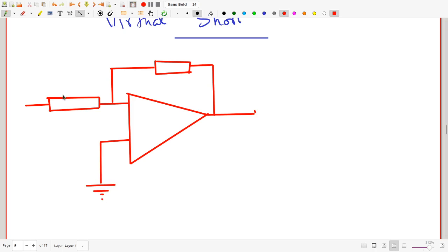So this is our inverting amplifier with two resistances, and let me just use two specific values here, 1 kilo ohm and 10 kilo ohms for the two resistors. This of course is called the feedback resistor and this is the input resistor, and here I have designed an op-amp circuit whose gain VO by VI should be minus R2 by R1, or minus 10 in this case.